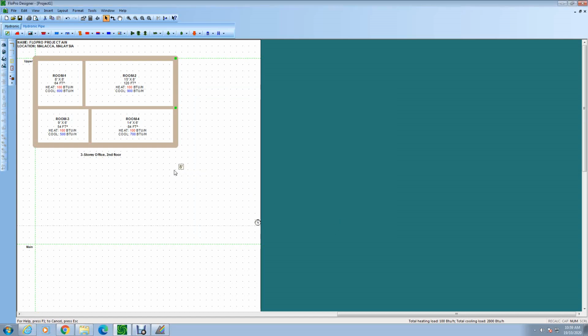Just click OK. Okay, now if we want to impose cooling load, and we want to include the fan coil, so you go to impose load cooling. Here above you can see there are impose load, heating and cooling. There is hydronic impose load for heating. There is impose load for indirect water heater. There are many different kind of loads, so you have to really select what you need.